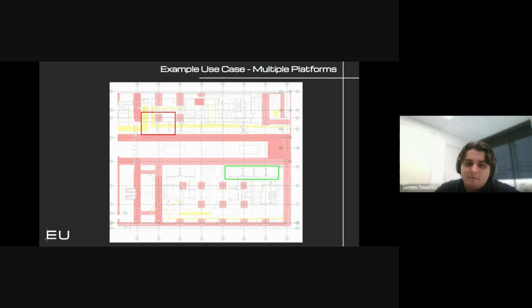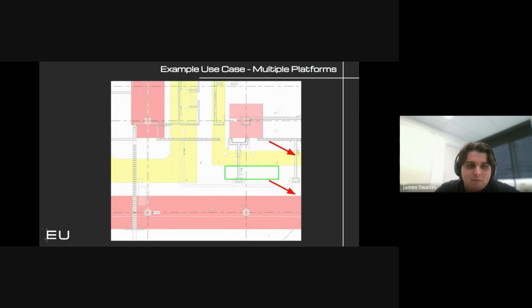However, if we zoom in on this red area up here, now those arrows are still showing up. It's not ideal. In these little red sub areas, you can see that there's an electrical duct bank right underneath, and we're missing a lot of cores. So the time between me making this report and our site team getting enough access to this area to actually begin scanning and looking for new cores is going to be about 5 months. So in this case, well before we've got continuous access to the space, we can start weighing our options and mitigating the risk to the schedule that comes from having to get this area redesigned only in the moment once we're there to assess it up close.